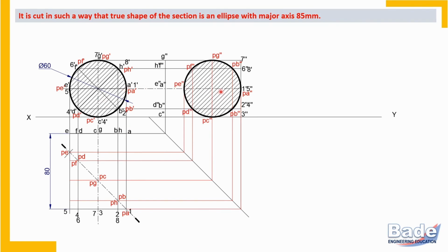Remember now, we are going to make a retained portion dark. In case of cylinders, only boundary of the retained portion you should make dark. Now here in front view, this entire circle is at boundary of the front view only. So sectional front view is over.